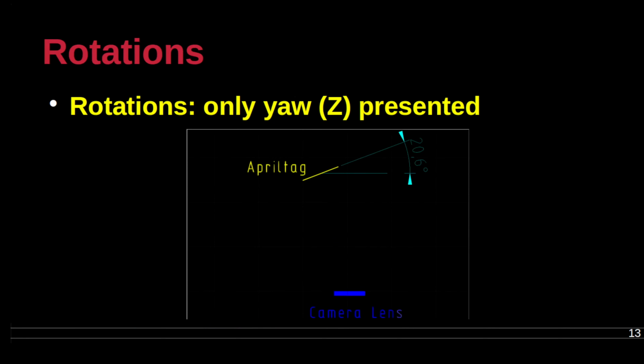For practical purposes, the yaw values from the AprilTag target and the IMU are applied to coordinate the precision turns for the robot. Since the AprilTags will be stationary, a nominal assumption until the Game Design Committee releases Game Manual 2, the turning will be performed by the robot where the IMU resides. A good combined algorithm will probably rely on a control algorithm for the turn using IMU data readings and using AprilTag results, if applicable, as an augmented filter.